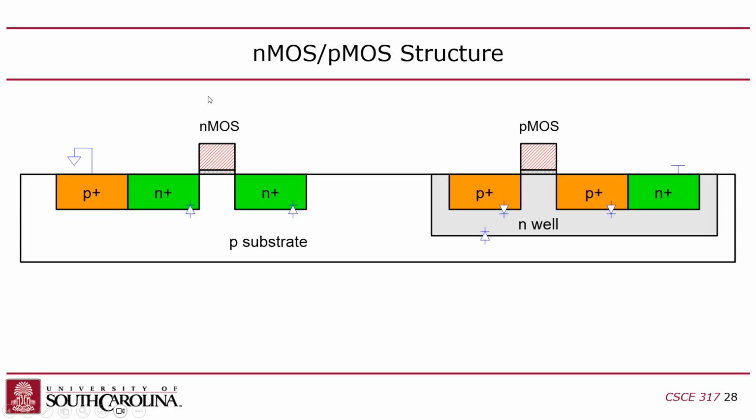But at the same time, the diffusion areas, which is the output of the gate, they're also capacitors because a reverse bias diode is also a capacitor. So now we get a double whammy here. We get a capacitance on the input of the gate, and we get a capacitance on the output of the gate. And if you connect the output of one gate to the input of another gate, you got the capacitance of the diffusion area added to the capacitance of the gate on the downstream, on the successor gate, right? The guy you're driving, right? That's real bad. And that's what causes chips to be slow.